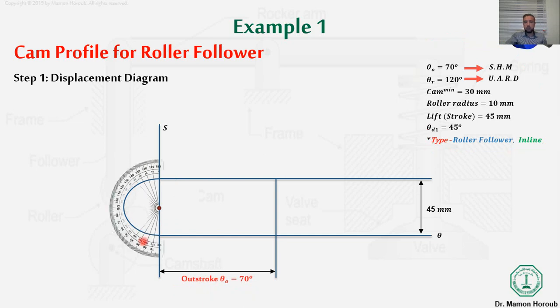So first of all, this is what we always follow, I need to divide this circle into 6 pieces. If I have this half circle 180 degree, that means every piece will be 30 degree, and based on the picture, every 30 degree I will put a line, then I need to put a dot between those lines, as well as the cross between those lines and the half circle.